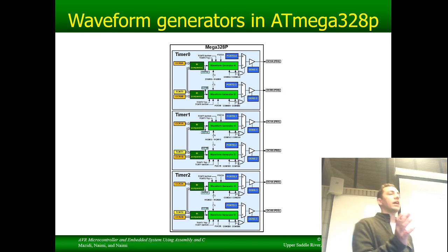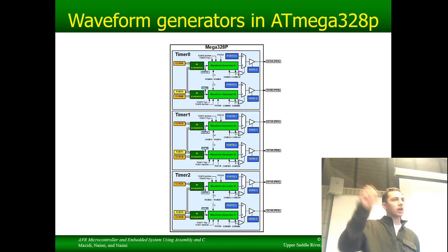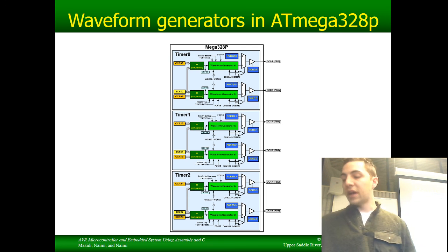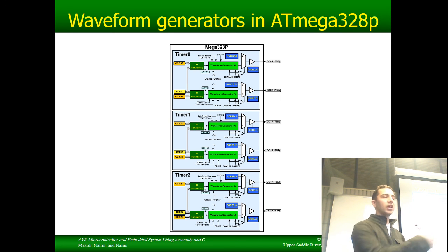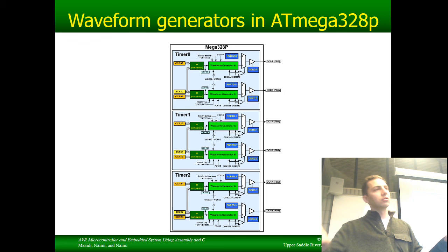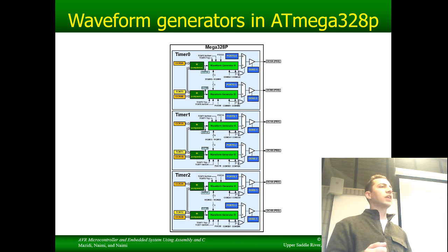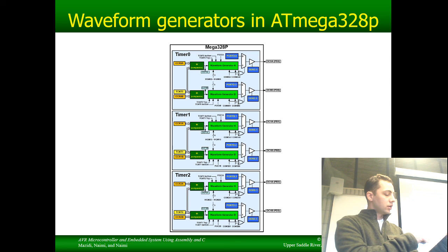So you know what you have to fill out, and you can go through, check them off, all right? That's all you have to do. When you're writing any program, if you're using a particular peripheral, just look at each grouping of bits. Force output compare, don't know what those do. Look it up in the manual. Oh, force output compare does a toggle. All right, well, I don't need to use that.